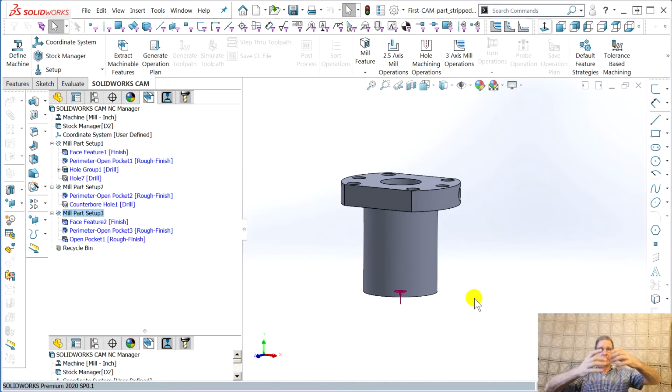And that's where you use a big tool to hog out a pocket, but then you can't get in the corners because the diameter of the tool is too big. So then it's smart enough to say, okay, I'll get a second, smaller tool, and I'll go and finish those corners, but I'm not going to go do the whole thing where there's error. I know just where there's material left, the remaining rest material, and I'll go finish that up. Meanwhile, the fundamental way the program works, it'll machine air all day long. So I'll show you where that is.